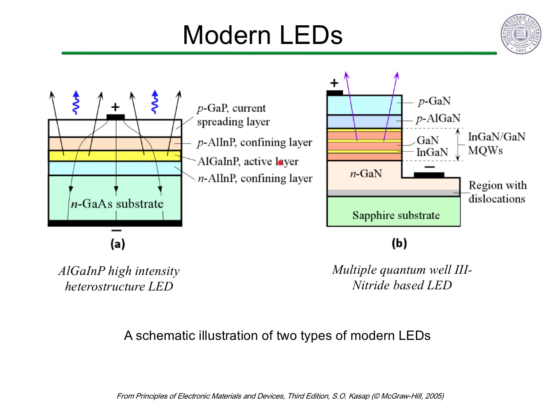The gallium nitride quantum well LED uses an aluminum oxide sapphire substrate to grow the gallium nitride as a barrier and the indium gallium nitride with a smaller band gap to make the quantum well. Here, a thick gallium nitride layer is grown first, where the interface with the sapphire substrate has many dislocations, which is avoided by placing the negative electrode above it. Multiple quantum wells are typically fabricated to increase the light intensity.